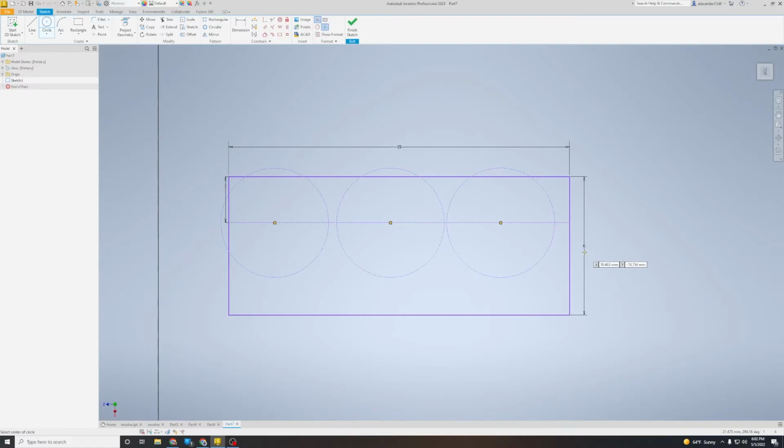You might have noticed that these circles all have dotted lines. That's because I made a mistake and did not turn off the construction line tool. To fix that is no big deal. I'm going to use the escape key to leave the circle tool, and then I'm going to click the circle that I want to change. Once it's highlighted, I can come up and click the constraint, and it will lose its dotted line. Repeating to the others, and we're most of the way there.